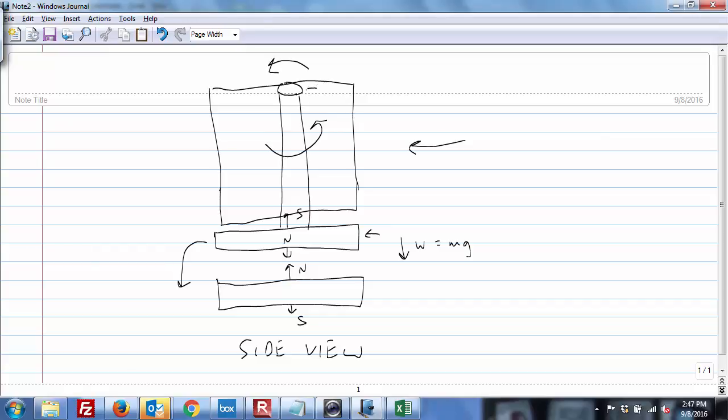These bearings are going to have to withstand the shear loads. This is the force of the wind. If you didn't have bearings on the top and the bottom, it would blow over. But the point is, the wind turbine itself is not sitting down. There's relatively little force of friction in the z direction, the vertical direction. It's approximately zero. That's the whole point.